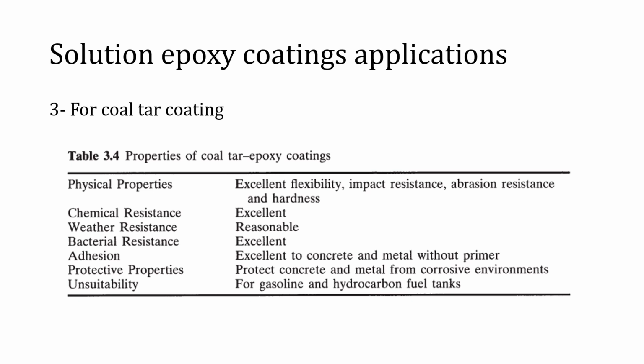Coal tar epoxy coatings can be used in various applications, particularly in tank linings, pipes, foundations in aggressive soils, sewage works, effluent plants, chemical processing plants, and dock and harbor installations. However, coal tar coatings are not suggested for tank lining materials for gasoline and other hydrocarbon fuels.